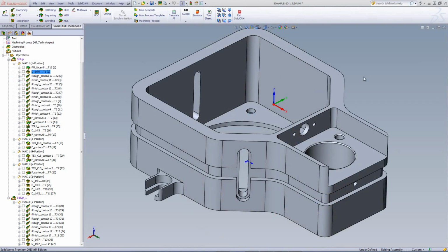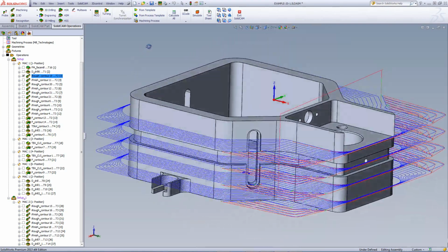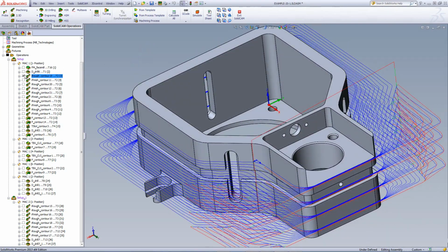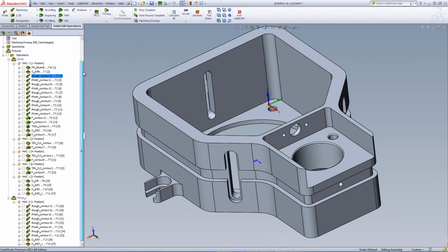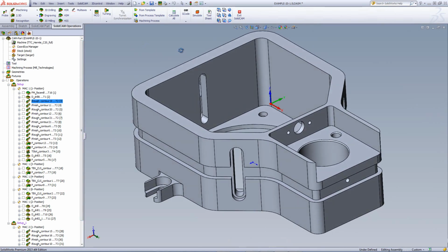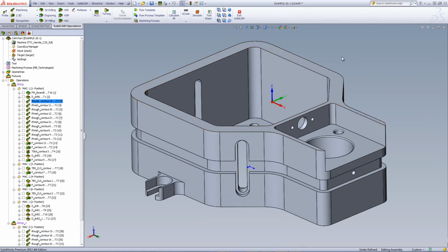Now I'd actually like to start removing my massive material that I have around the part, whether it be on the outside, this area over here, or the inside. I'd like to use now my iMachining option to remove the material efficiently and quickly. The first area that I did was the outside as shown over here. Now, before I continue, let's just take a look first of all at some of the settings that I've done for this part even before I start my iMachining.